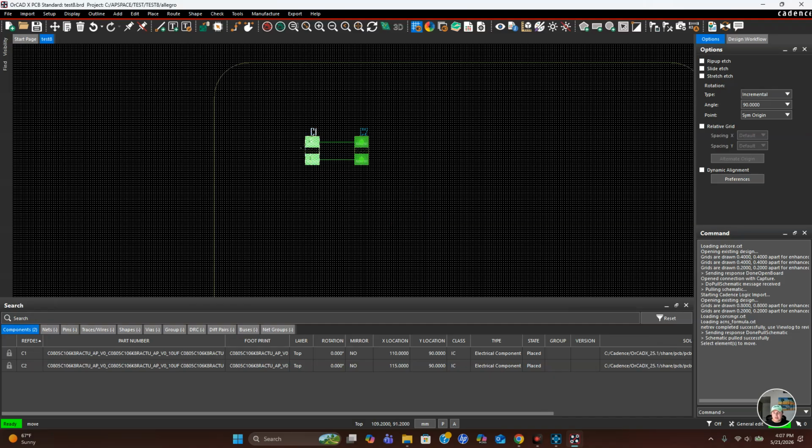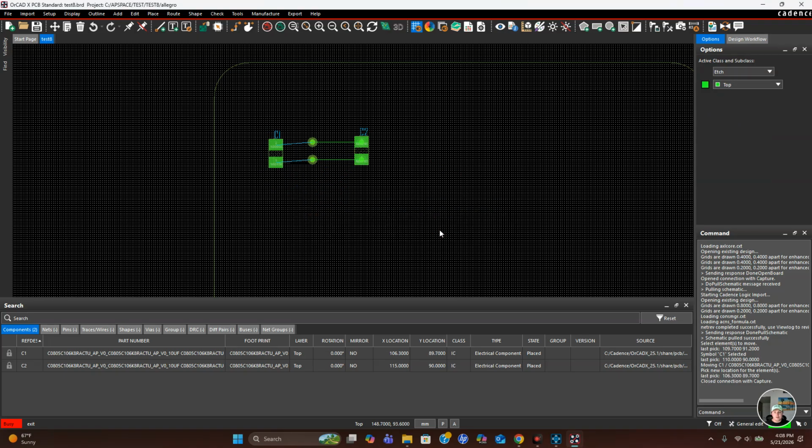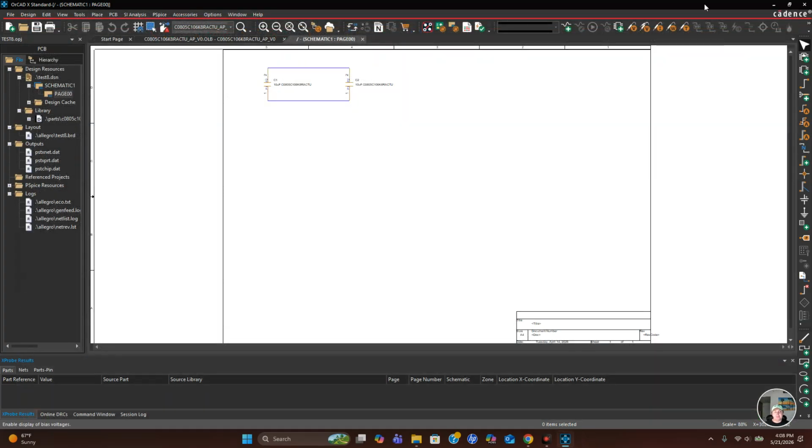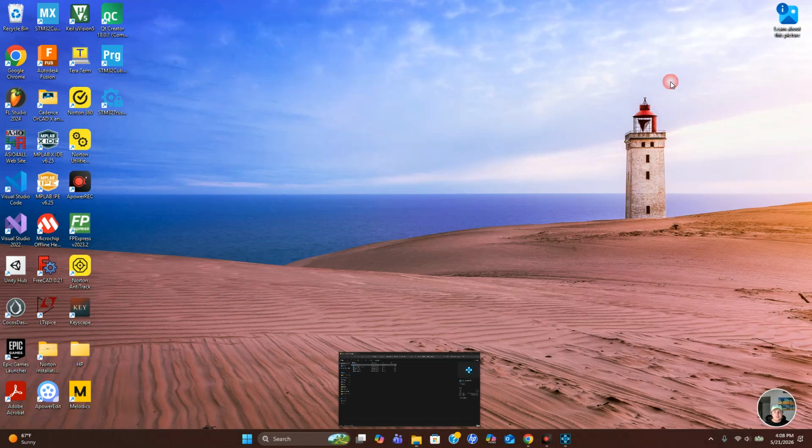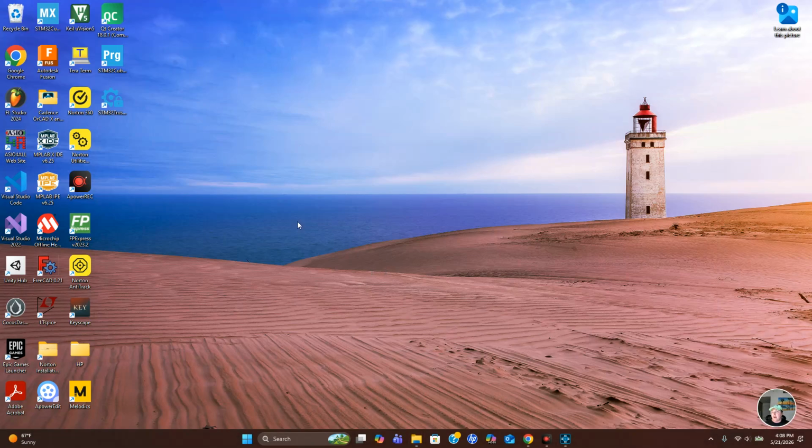And if you see here, when we start moving the part, the plus sign is on pin 1, and what we actually want to do is move the origin from pin 1 to the body center or centroid of the part. So to achieve that, we are going to open PCB Presto and shift the pads down is what we are going to accomplish here.